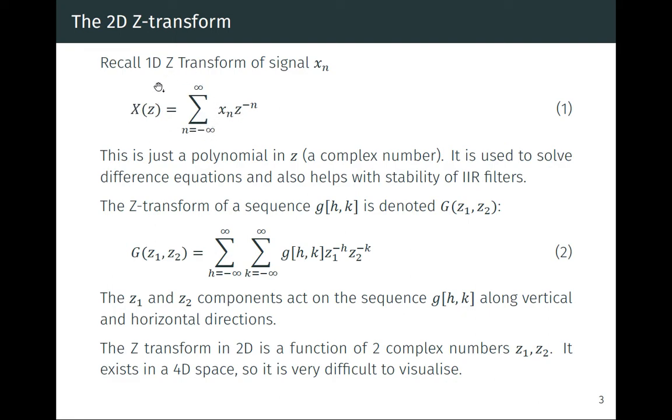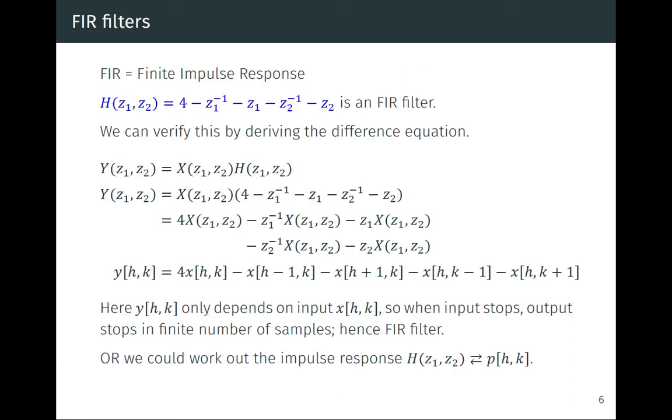That's the raw definition of your z transform: the infinite sum of these powers of z, and the power minus n is associated to the sample x_n. If you're centered in 0, then you have x0. If you're looking at the sample next to it, sample 1, that corresponds to the power z to the minus 1. So there's this minus sign, same as in the Fourier transform and so on. Something to remember here.